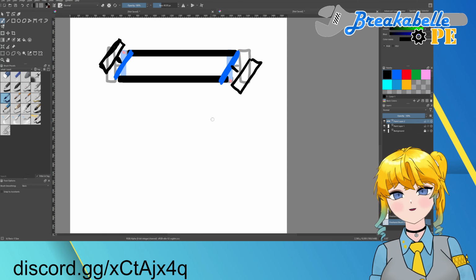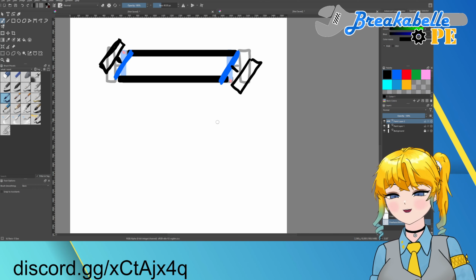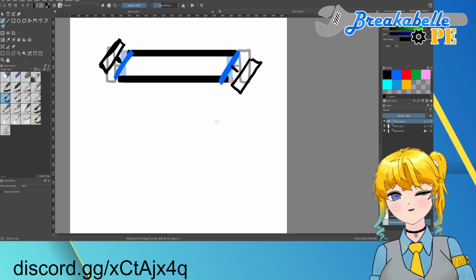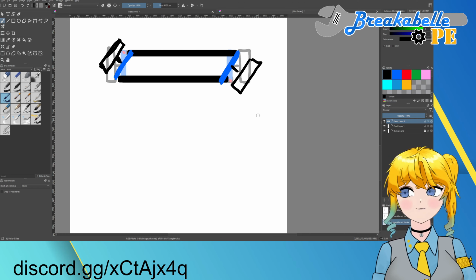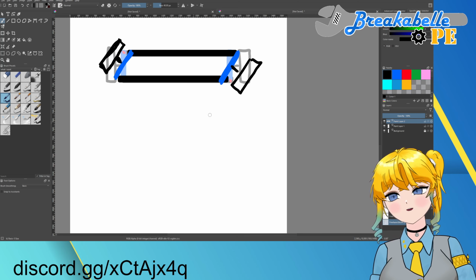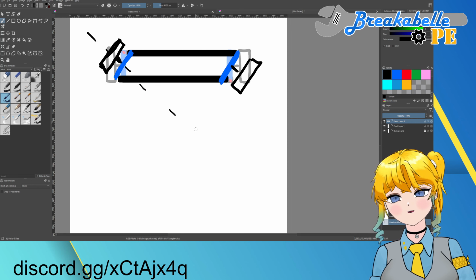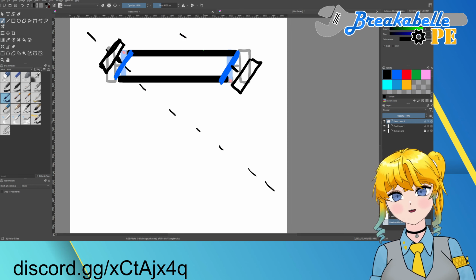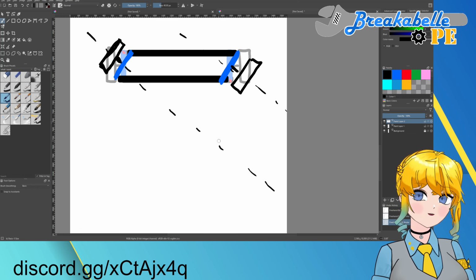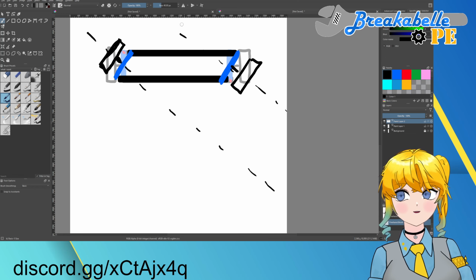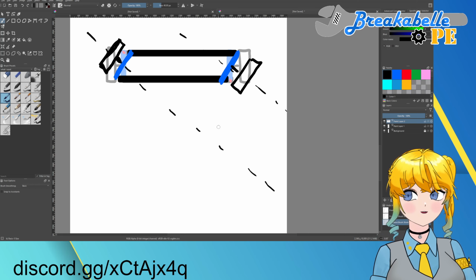But you might notice there's an issue. And that issue is what we talked about before, where when the car turns, every point on it needs to turn about the same point, which means there needs to be a point somewhere that is along the same axis of all these wheels. And since these wheels are parallel, there will never be a point, right? These lines will never intersect because they're parallel with each other. So you're never going to find a point. So how do we deal with this?